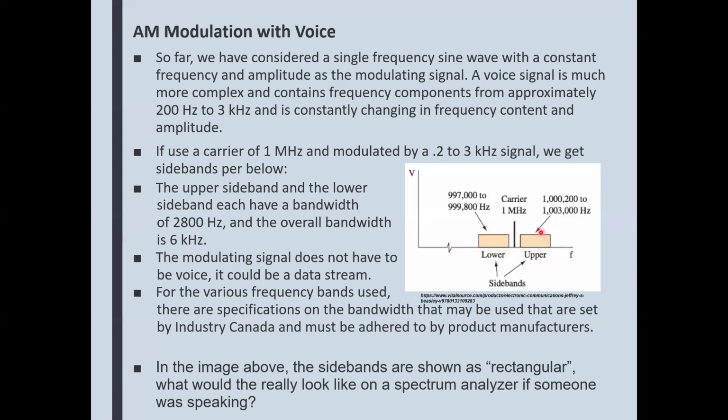And if you're transmitting a full carrier, you get pretty good power, because you get to use the power that is contained within both sidebands. And you get a little bit more quality of a signal, because you can spread the intelligence over the two sidebands. But if it's just voice, you can cut one of them off and fit more.